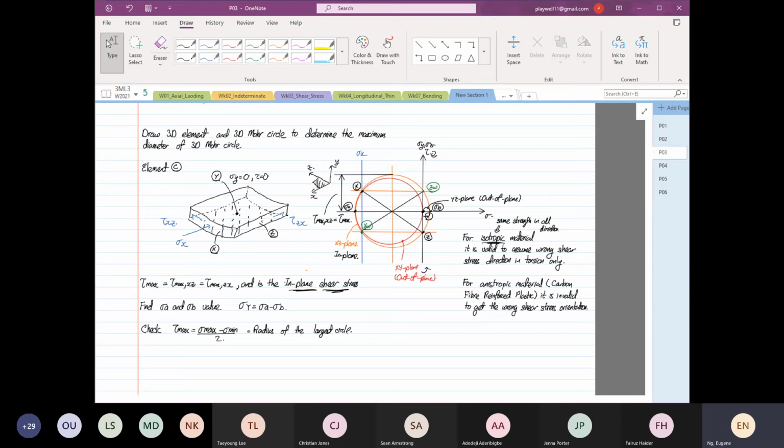Okay, so we know what we're going to find already. We know the process. We know the not process. We know what we have to determine. We have to determine our stress A and B value, compare with our yield. Then we're going to select the diameter first. The purpose is to select the diameter of the shaft. After we select the diameter of the shaft, we're going to check: is our stress above tau max or equal to tau max?